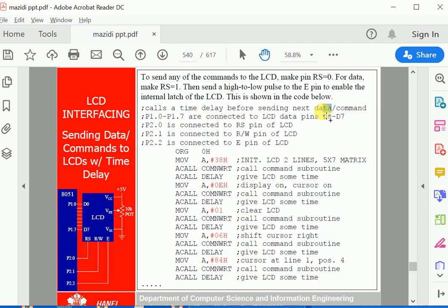If you are sending data from the microprocessor or microcontroller to the output device, and you have already sent one data, then you should wait for some time so that the output device can settle down, because input output devices and memory are very slow compared to the microcontroller or microprocessor.